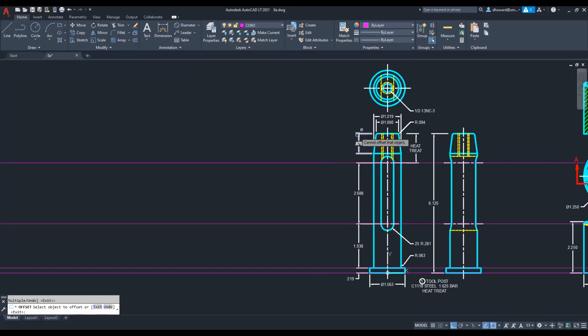The final offset is projected down from the top, but that's how it was given to us. So to get to the top, we need to do a full length offset, which is 6 and 1/8 inches, so 6.125 inches, sorry, 6.125. So from the very bottom all the way to the very top, that is what that distance is. And then you can project downward, 7/8, or 0.875. And so now you have all of the horizontal lines.